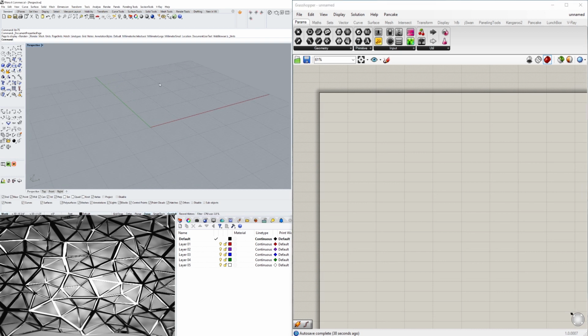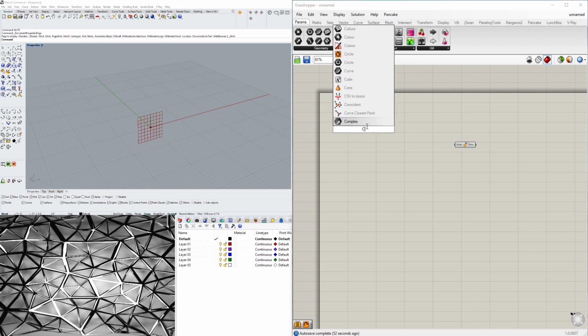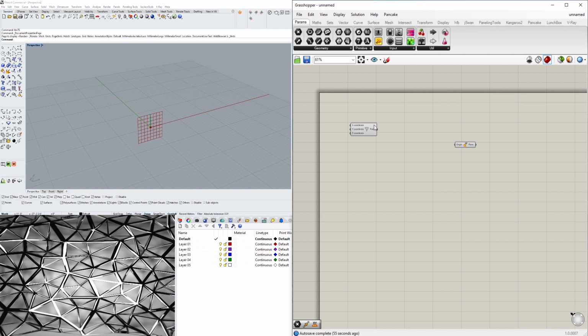Now let's create a plane that is upright in the XZ plane. So I'll go ahead and bring in an XZ plane. And typically we could just use this XZ plane, but I like to give it an origin point. So I'll go to construct point, and this way we can use that point at 0, 0, 0 as our origin point, and we can move it around this way. And in between that I like to bring in a point component. This way, we can set one point and move that around if we need to. So that's going to be our original plane.